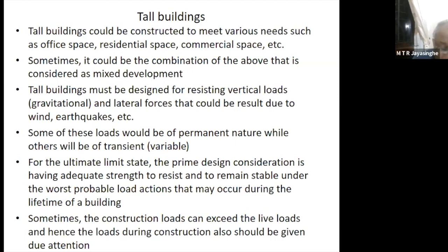In that building, it looks like they have not considered the construction sequence effect when they were designing the building, and because of that, they have under-designed the transfer plate by a small margin. But this kind of small margin can cause slightly higher crack widths, and with a slightly higher crack width, you will find the whole structure is okay except the transfer plate, because the transfer plate has undergone a higher degree of deterioration than the rest of the building.